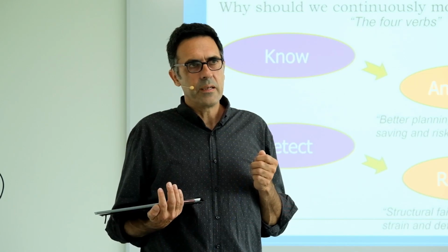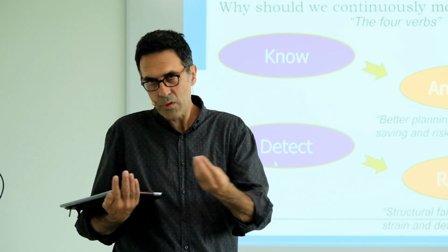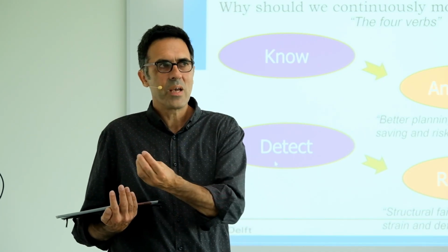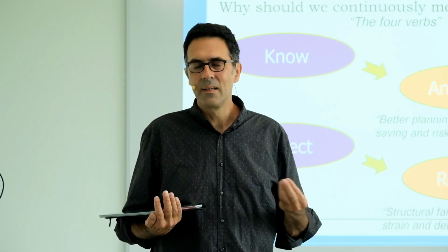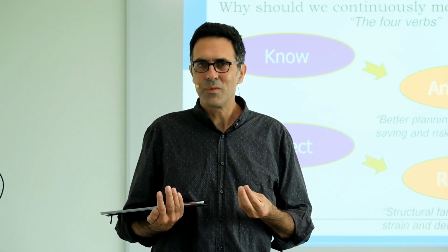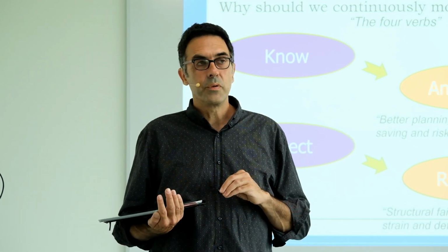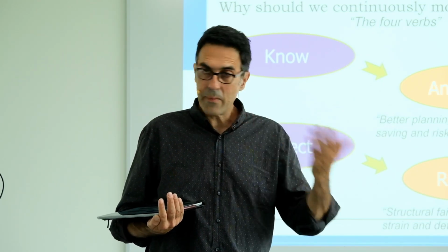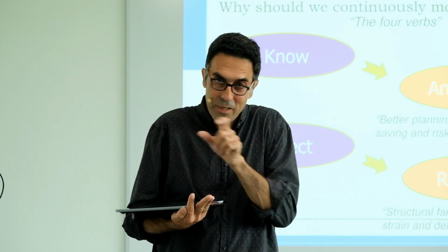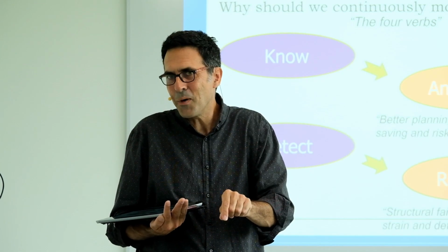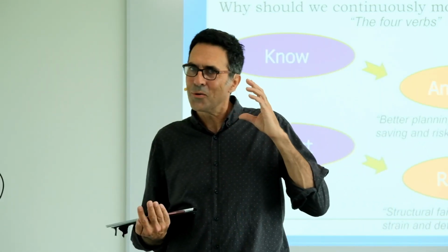So that means if we have such a scatterer, we detect it still in the radar coordinate system, the radar frame, but then we have to compute where that point is in the real world, right? And that is actually difficult. So it's uncertain. If you put, for example, Google Maps or Bing Maps beneath, it can be that as you keep on zooming in, the point will not be exactly on that spot. This is also why courses like this are important, because you need to understand that.